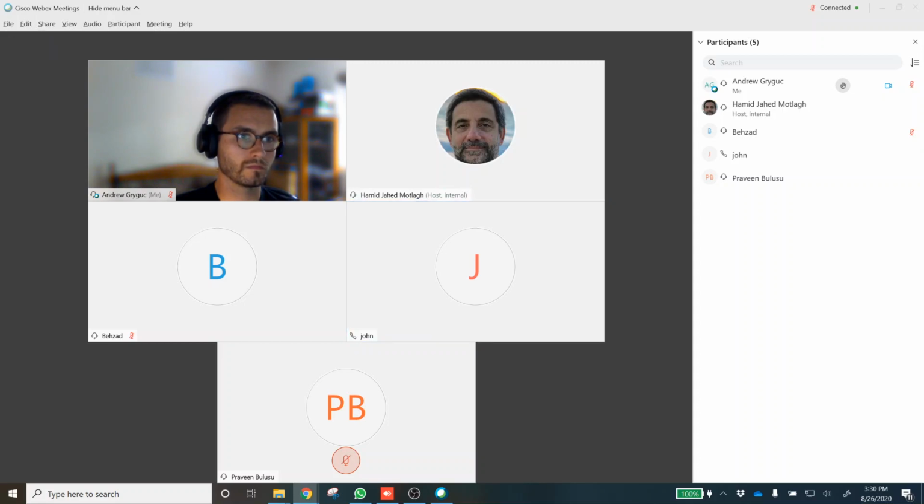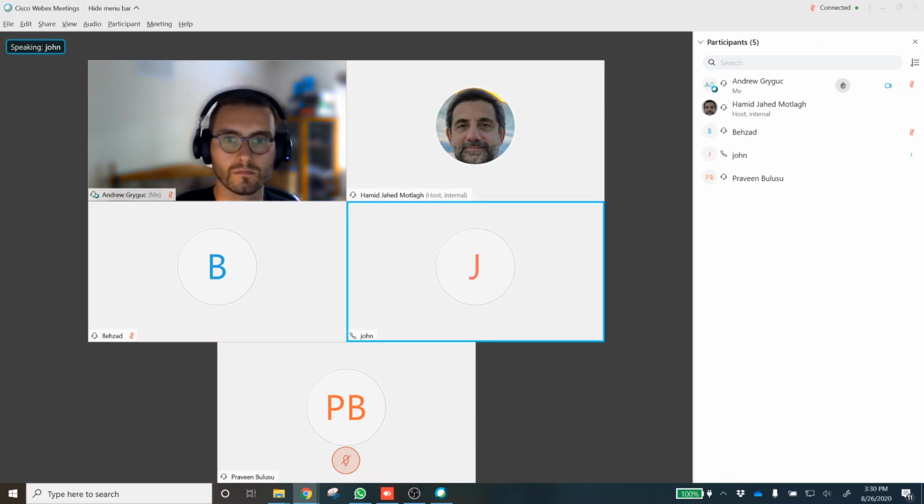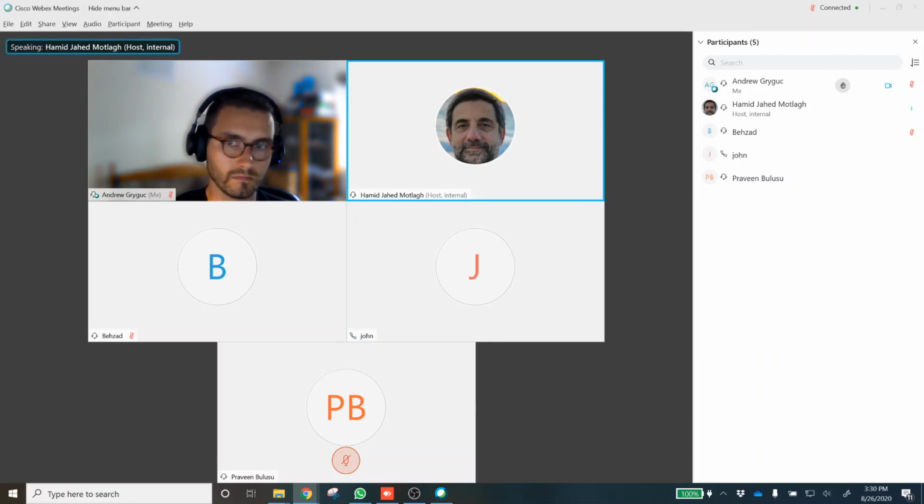Okay. So the additional test which we need to request is the strength test with and without case hardening. That will give an indication of what should be used. And those are quasi-static tests that you want to be done. Yeah. So doing quasi-static tests on as received material, and the same on the case hardened material, to just have a comparison between the properties of the two.